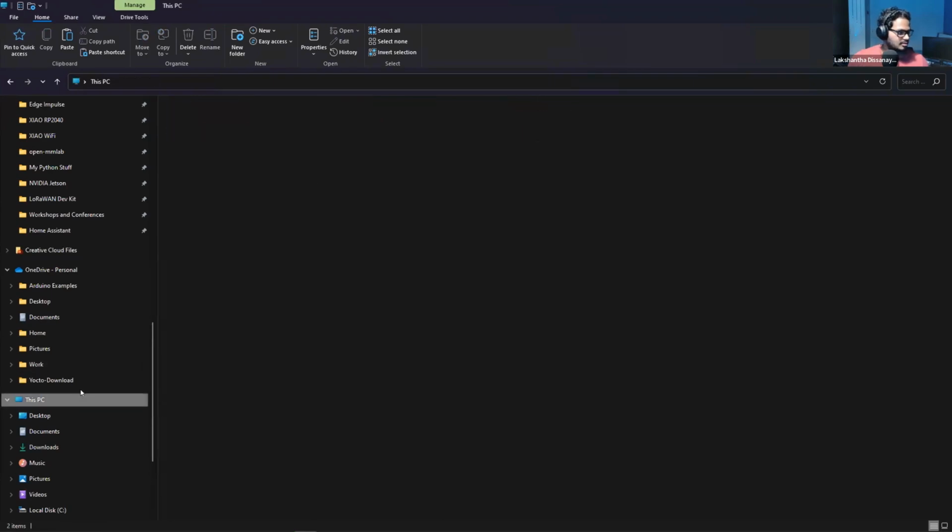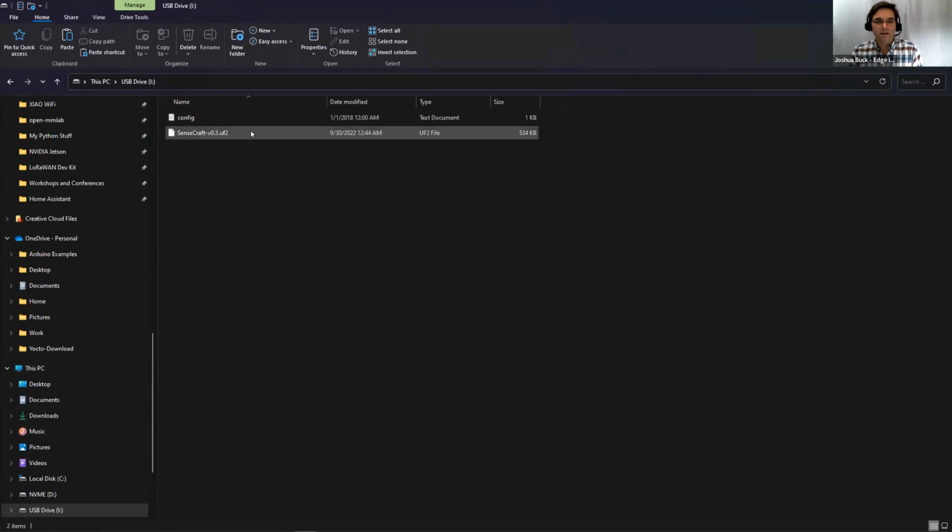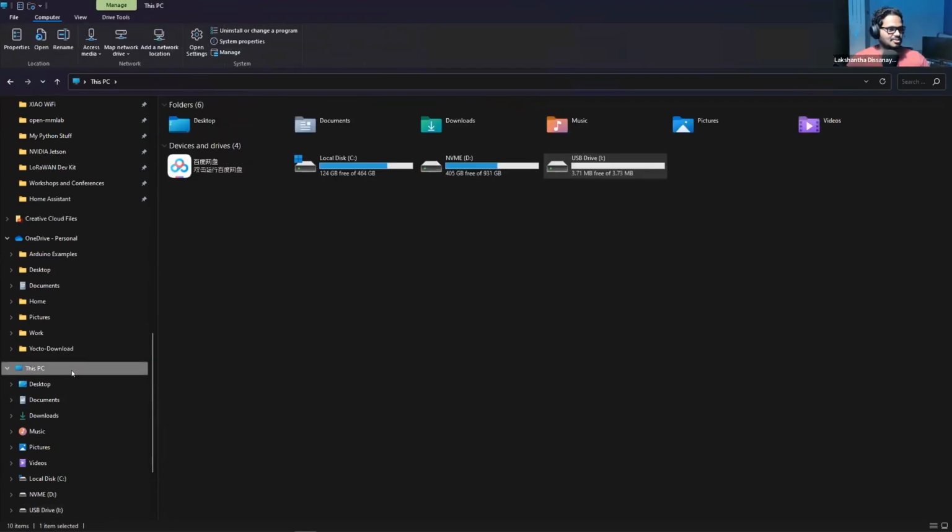Okay, so you might need to back up 1 or 2 steps. Did you see the device booting into the bootloader mode? Correct. You have to double click this button, and then it will enter the bootloader mode. Once it enters the bootloader mode, it will show this. Can you see this Arduino mass storage device? Yes, we can see it. Okay, so this is the mass storage device.